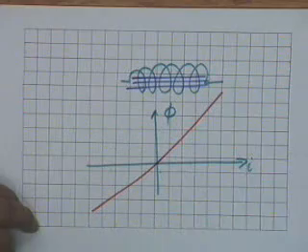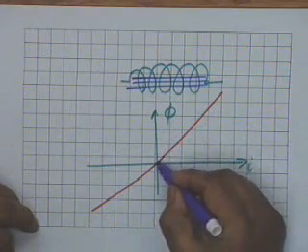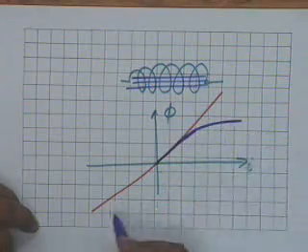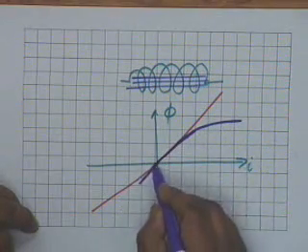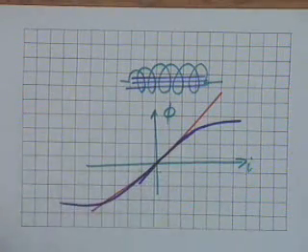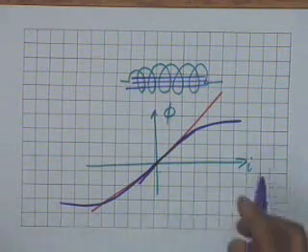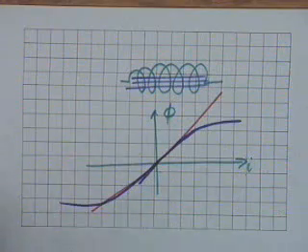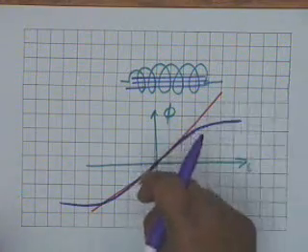That is, what happens is that up to a certain extent, it's linear, and then the flux tends to get saturated. Similarly in the other direction, it tends to get saturated. And you know that if you bring back the current to the previous value, it does not follow the same path, and that's this famous hysteresis phenomenon.